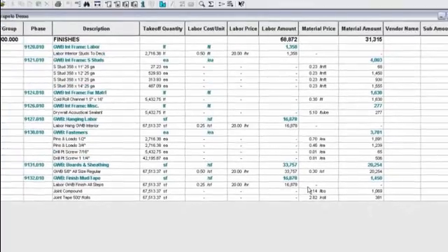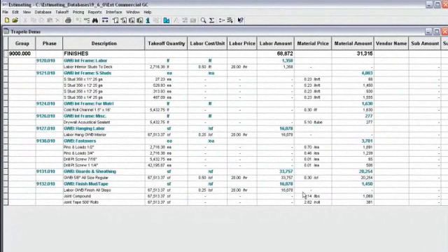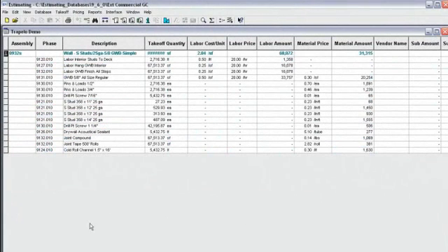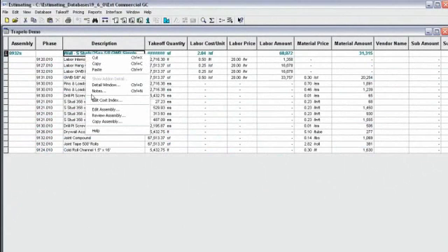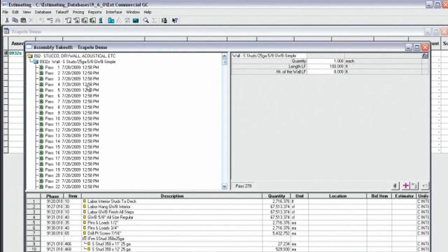The best way to review the estimate created by Autodesk QTO is to use the Review Assemblies mode within Sage Timberline Office Estimating. You can see how each wall within the model has created a pass in the assembly takeoff, and further the specific quantities that populated the variable entries. As you click through the different passes, you can see the length and height of each wall are populated with the specific quantities from the model.